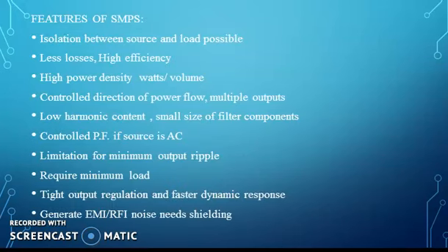The features of SMPS are: isolation between source and load is possible, less losses, higher efficiency, high power density, control of direction of power flow, multiple outputs, low harmonic content, small size of filter components, controlled power factor if source is AC, limitation for minimum output ripples, requires minimum load, tight output regulation and faster dynamic response.